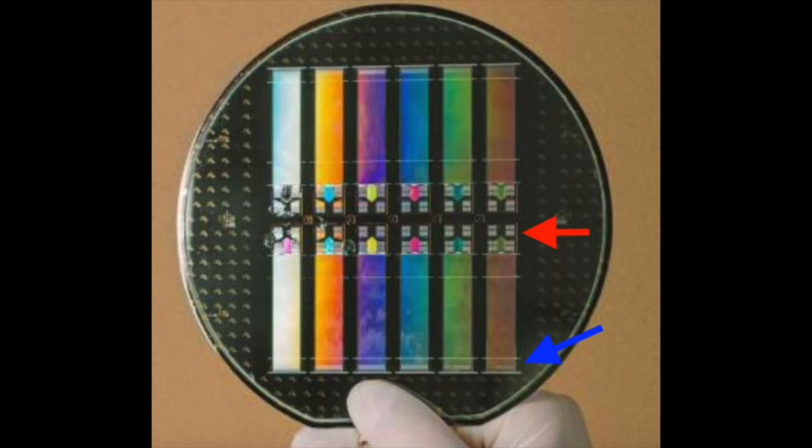This is a picture of the microfabricated threads for 12 different Neuralinks, probably of 1,024 channels, assuming 4 by 256 channel architecture per unit. The red arrow points toward the proximal end of the link, where the threads interface with the rest of the Neuralink hardware stack, and the blue arrow points toward the distal end of the link, where the threads are inserted into the brain tissue.